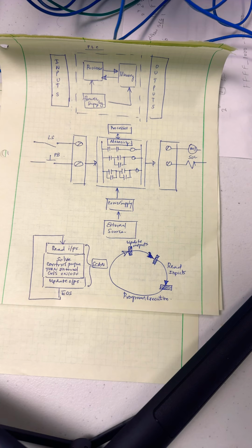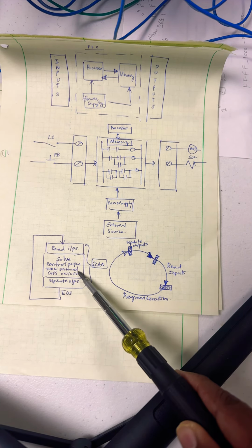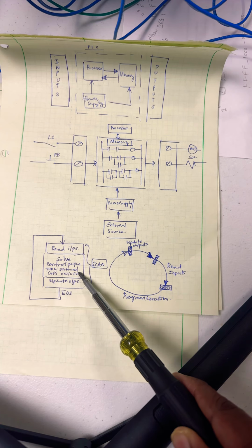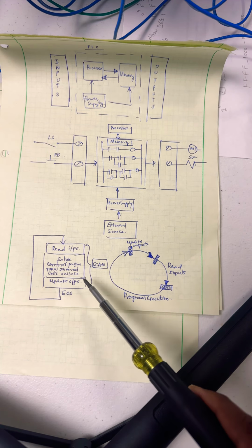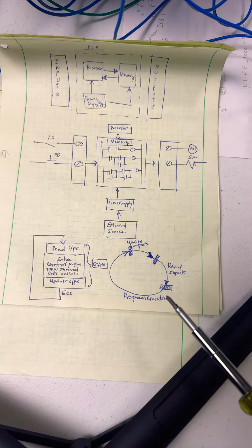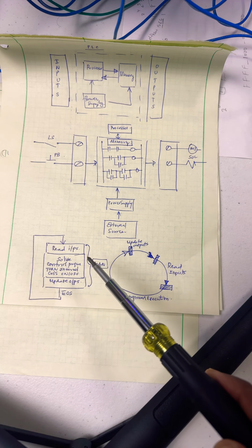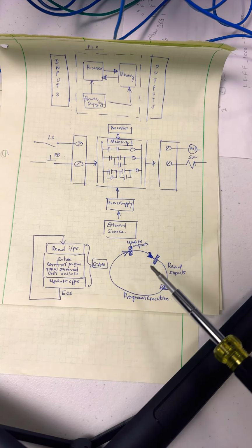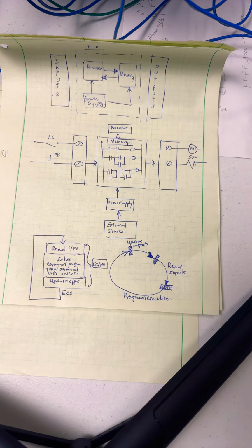The energizing or de-energizing of these internal coils will not, however, turn the output devices on or off. Once the processor has finished evaluating all the control logic programs that turn the internal coils on and off, it will perform an update to the output interface modules, thereby turning the field devices connected to each interface on and off. This process of reading the inputs, executing the program, and updating the output is known as a scan.